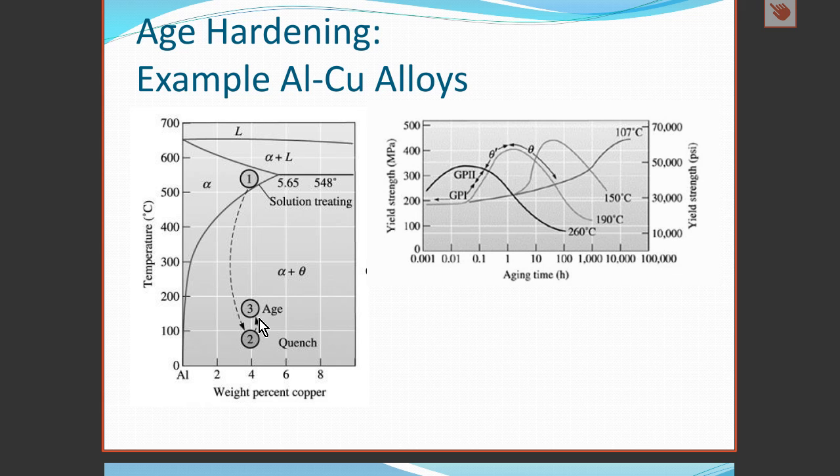Through heat treatment, a process called aging, the precipitates, the second phase, which is thermodynamically favorable under equilibrium conditions, begins to precipitate. These precipitates are very finely distributed because the precipitation is occurring in the solid state at a low temperature. This means that diffusion kinetics are slow, and large grains or large precipitates will take a long time to develop.